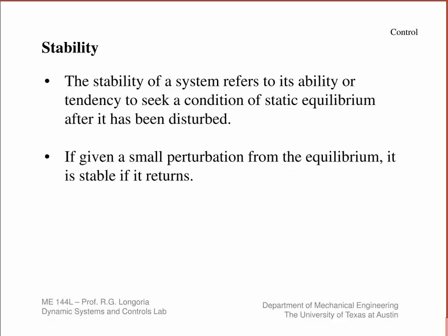And so when we looked at that overshoot, for example, we said that was relative stability: it can oscillate away from the point that you want to go to, but it comes back, right? When we talk about absolute stability, we say it's stable or it's not. In other words, if we perturb it away, it just keeps growing and goes unbounded. So absolute stability is a measure of whether it's stable or not. It doesn't say how well it's behaving. It just says, look, it's not stable or it is. Okay, so there's a difference in the terminology, absolute versus relative.